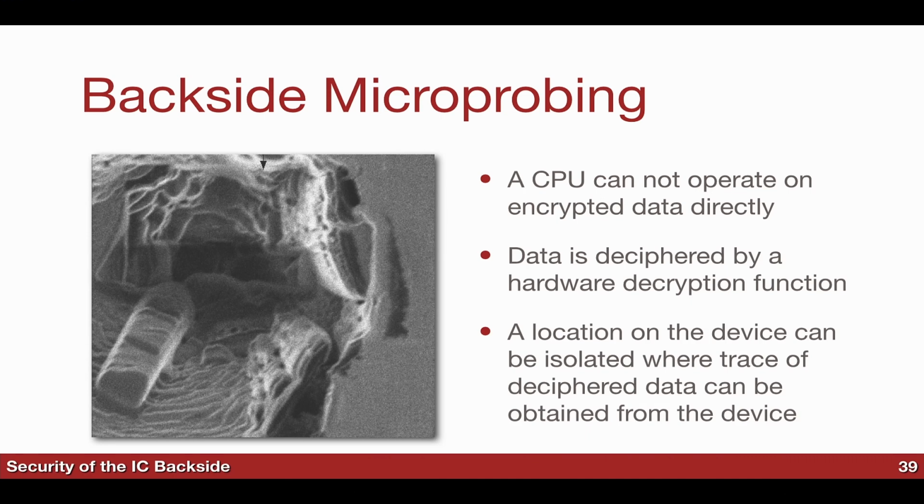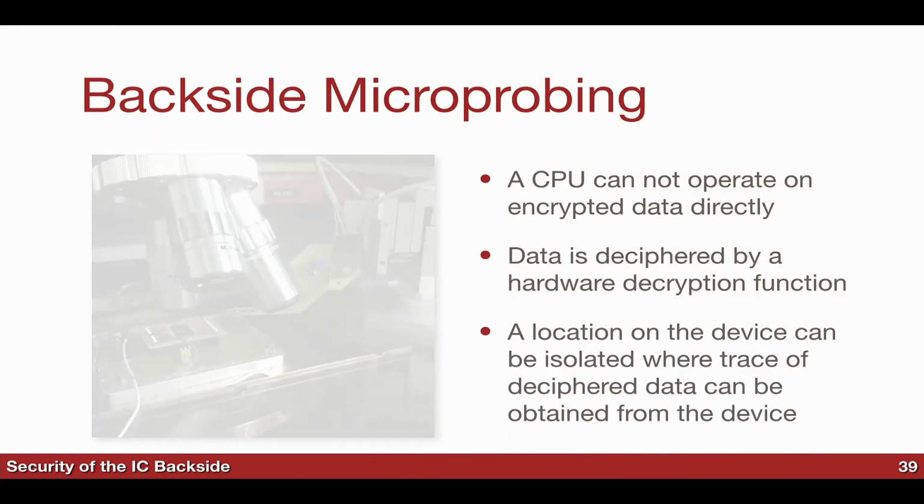The interesting thing is, when I showed this to Chris, he said that's the dirtiest FIB he's ever seen in his life. And he's right. But the thing was, we screwed up. The first time we shorted out 2 of the wires when we were doing this in the FIB. But the nice thing about the FIB is, if you short 2 wires, you can disconnect them with a different gas and then connect the wires using a different gas where you deposit metal. So now we fix the chip, and we can come down and probe the chip as we wanted before, which looks like so, approximately.